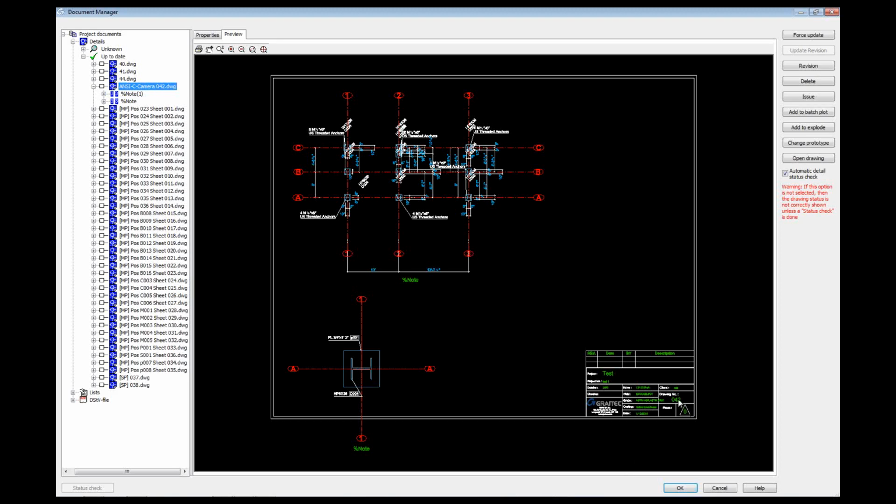On the title block, it won't show up because those are tokens, and the tokens are from the info that is on the 3D model. This one has nothing to do with the title block. So I guess you have to do it like you showed us how to do the shop drawings the other day. Do you modify the erection plan title block like you did the shop drawing title block, where you can change that token? Yep, just change the token for all your title blocks, and that will do the job.